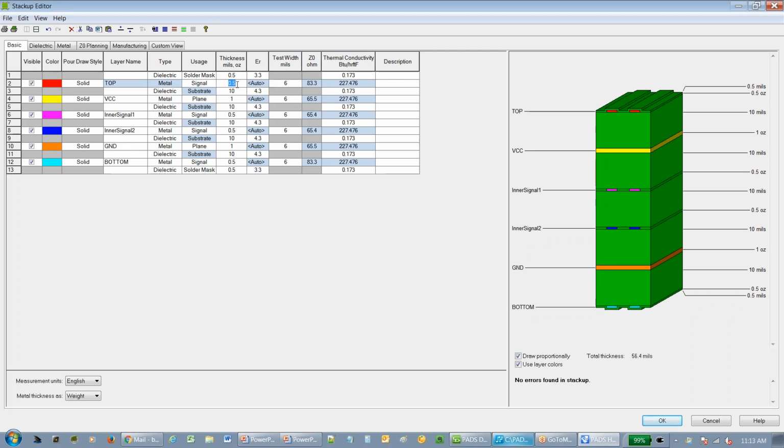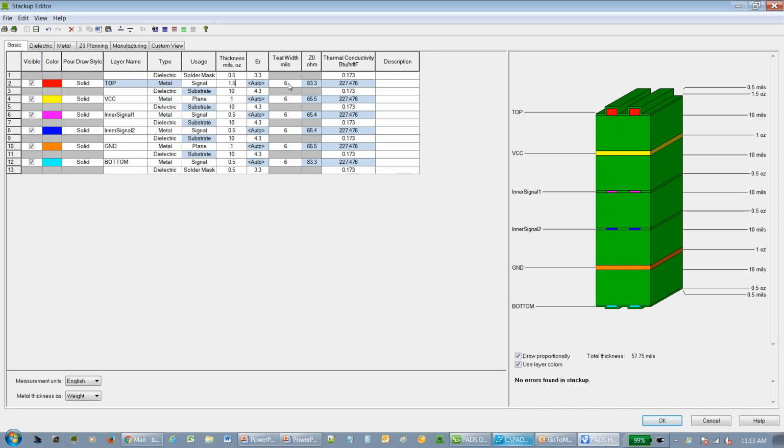So you'll see the impedance there was 83 ohms, by just going to 1.5 ounce copper, that changes to 78 ohms. Again, getting closer to something that the driver technically wants to see and helping reduce that ringing and overshoot. The dielectric constant of 4.3 is quite average, but a lot of materials out there are around 4.8. You could choose materials that get you down to say 3.8. And again, you can play around with the impedance of that trace just by changing the dielectric material.